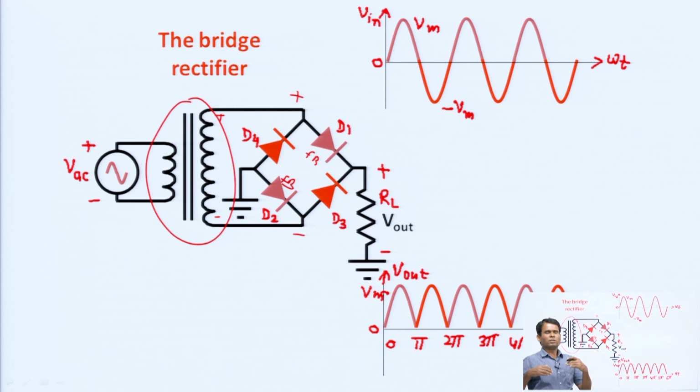Since the size of the center tap transformer is bulky and larger, the mobile charger will be heavy, and since more copper wire is used, the weight of the mobile charger will increase, copper loss will increase, size will increase and cost will be more.